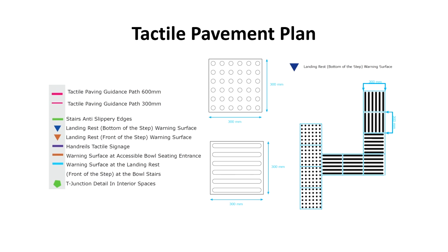Now, while planning a pavement plan, we first start with the design phase. This includes identifying key areas where tactile paving is needed, such as near the staircase, ramp, or pedestrian crossing. In our example, let's consider warning paving in front of the staircase.